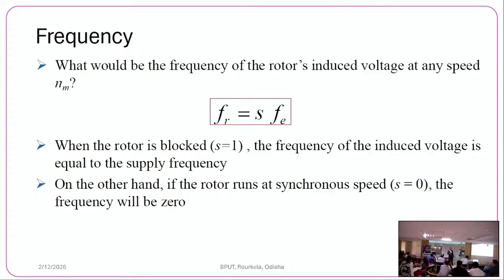For a six-pole machine, it will be one-third of that. So there is a mismatch between omega equal to 2 pi f, which you use in the reactance formula, and the synchronous speed. So for that we define what is called electrical speed.